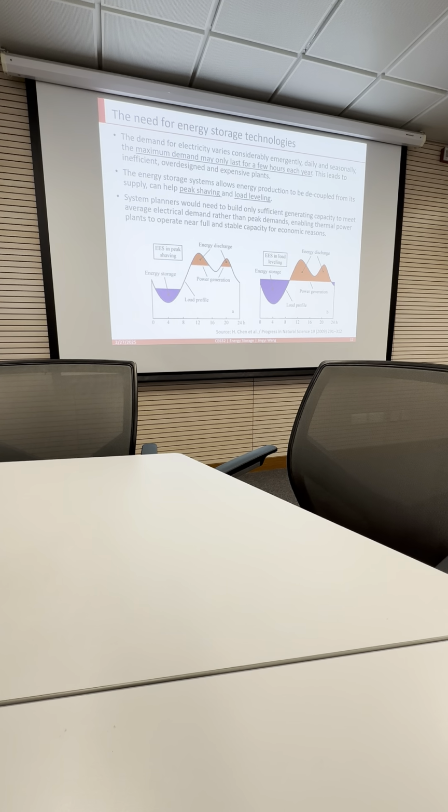Also, there is other usage for energy storage technology. For example, when we design an electricity generation system, there may be some maximum demand that will only last for a few hours each year. That means the peak hours may only last for a few hours each year. So if we design and build a power generation plant based on the peak demand, there will be a waste because it only operates for a few hours each year.